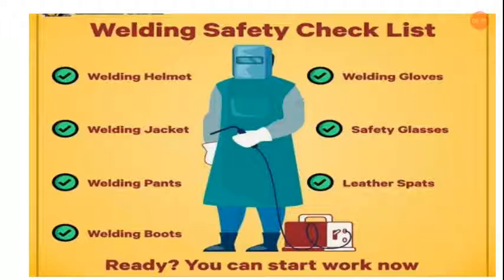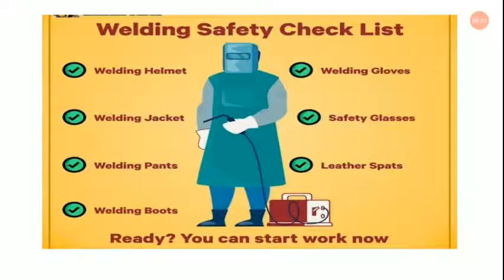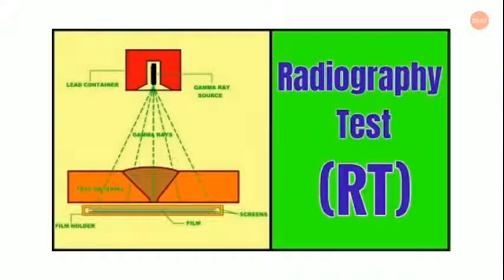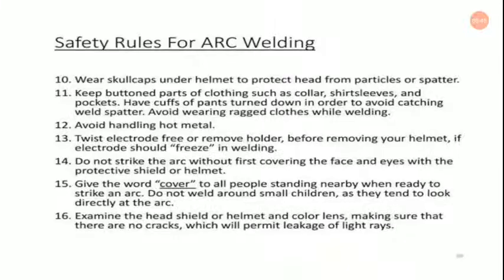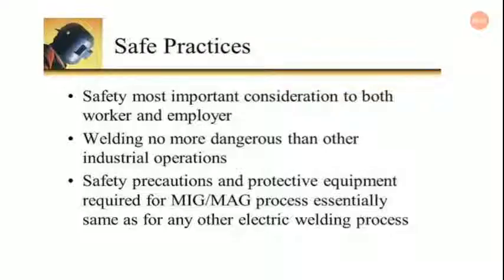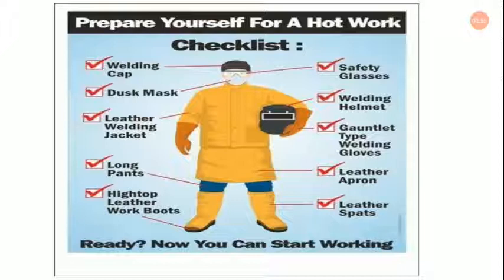Besides not looking at an arc, the only other preventive measure is the use of proper eye shading filters. The general rule is to choose a filter too dark to see the weld, then move to the lighter shades without dropping below the minimum protective rating.